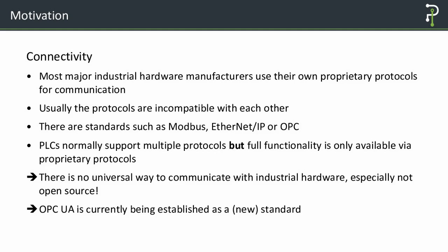These protocols are usually incompatible, and even for single vendors, new versions of the device may have different protocols or outdated protocols. So it's quite complex. There are some standard protocols on the shop floor. A very old one is Modbus. Ethernet/IP is newer, and the newest one is OPC UA. OPC DA is a bit older. Those protocols are supported by several devices for specific purposes, but usually it comes at a price, because all the functionality a device or a PLC controller provides is only supported in its native protocol. It can do some things via, for example, Modbus or Ethernet/IP, but not everything.